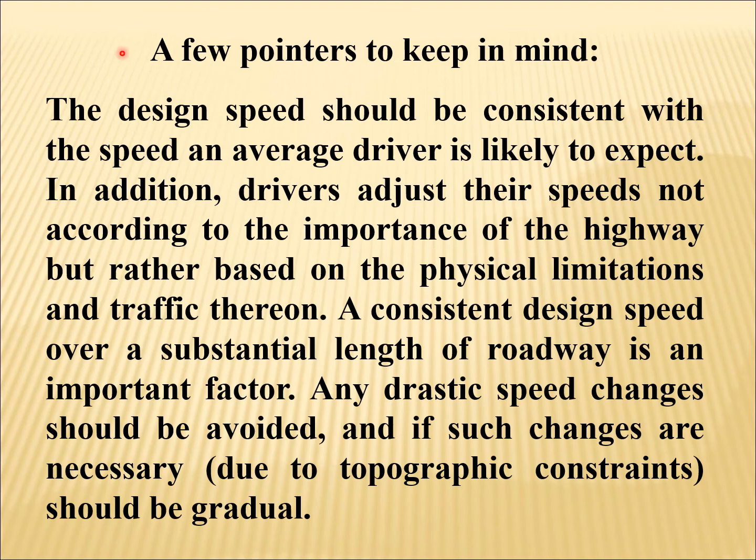A few pointers to keep in mind. The design speed should be consistent with the speed an average driver is likely to expect. In addition, drivers adjust their speeds not according to the importance of the highway but rather based on the physical limitation and traffic thereon.